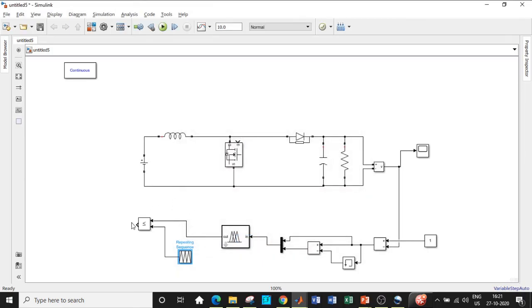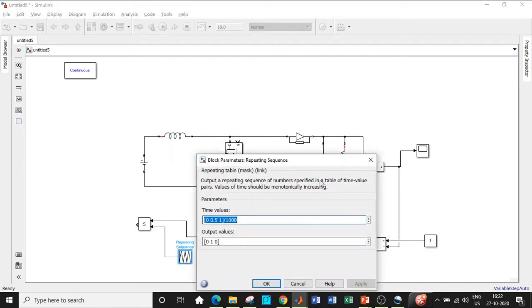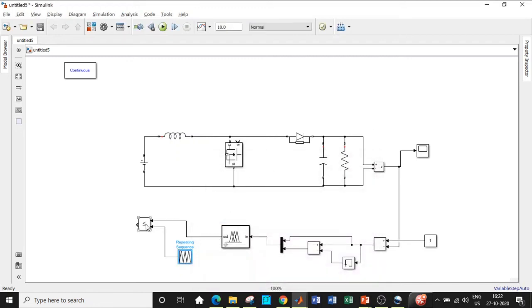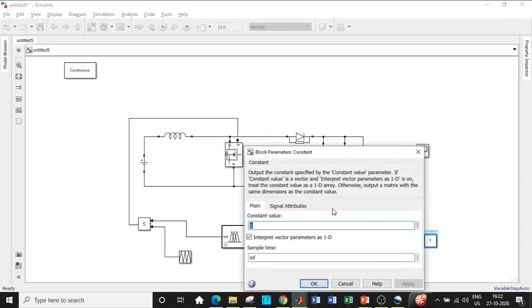So this is basically just like the SPWM technique, comparing the output value of the signal, the reference signal, with a carrier wave that basically has a triangular waveform in nature, and consequently the output that is produced will be in pulse form, and that will be given to the gating terminals of the MOSFET switch. Over here I have to enter the value of output voltage that I want. It should be increased to 48 volt.